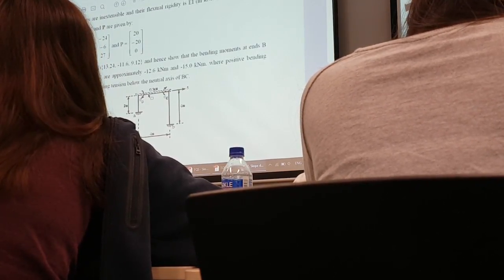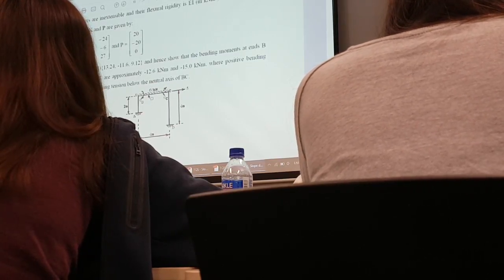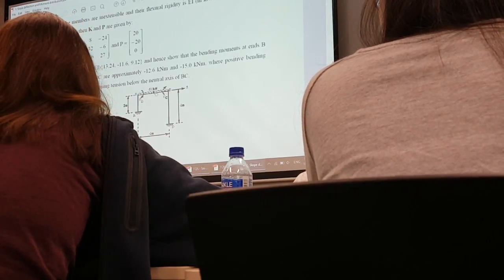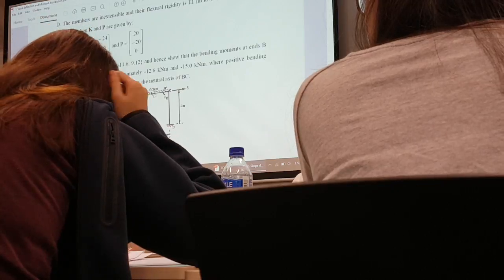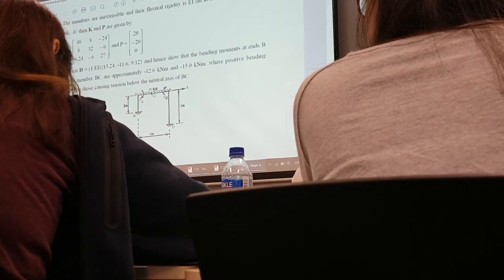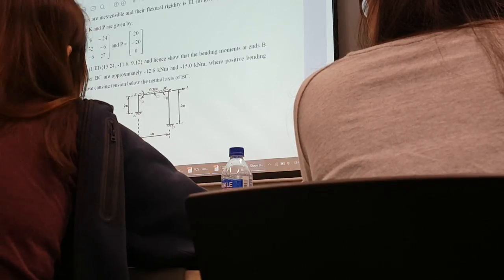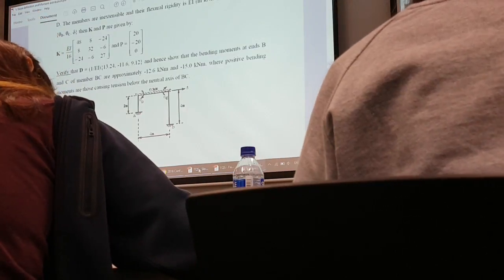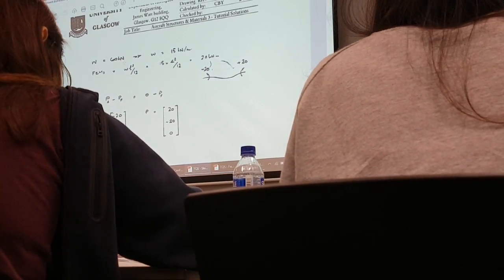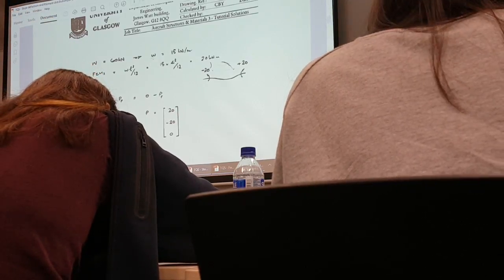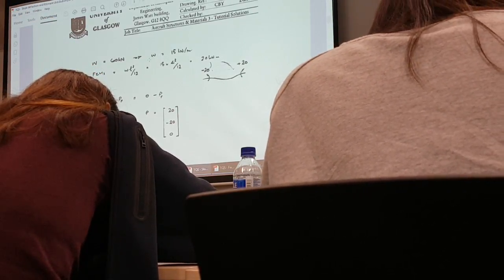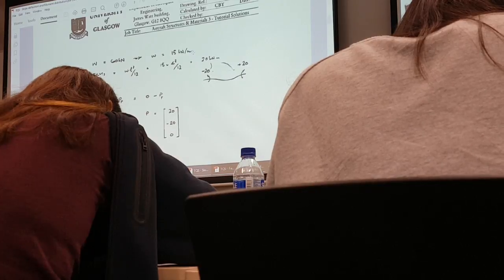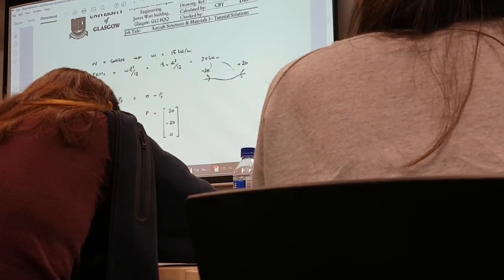If you're talking about a small w, it has to be per meter. Uniformly distributed load usually comes in newton per meter. But this question is tricky. It tells you 60 kilonewton already, so it's no longer newton per meter. If you use this 60 straight away in the formula, you will not get it right. So the entire capital W is 60 kilonewton, and you have to find the small w. The small w is 15 kilonewton per meter because the length is 4 meters. So you need to determine the small w.